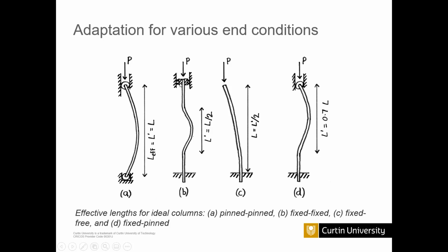So this end is fixed, frozen like that. Then we will see this kind of buckling, but it is not the large loop. It is half of this length. That means even though the column length is L, the buckling will generate over half of the length. So L effective equals L upon 2.